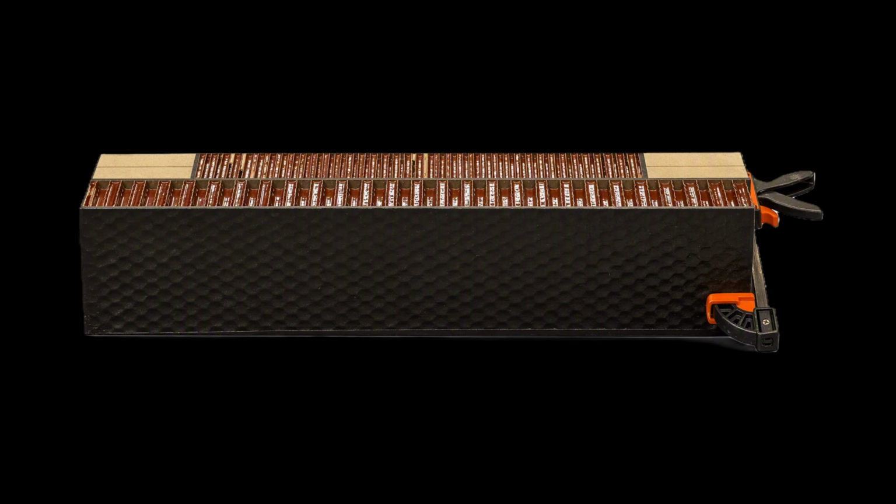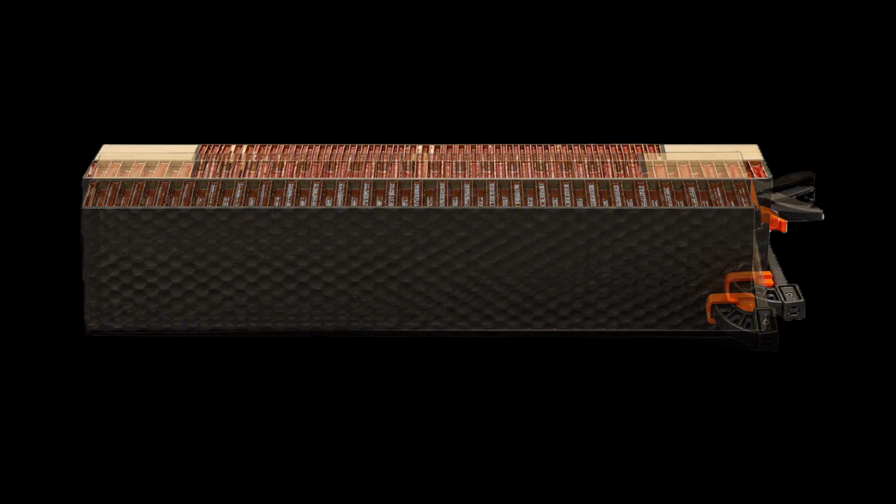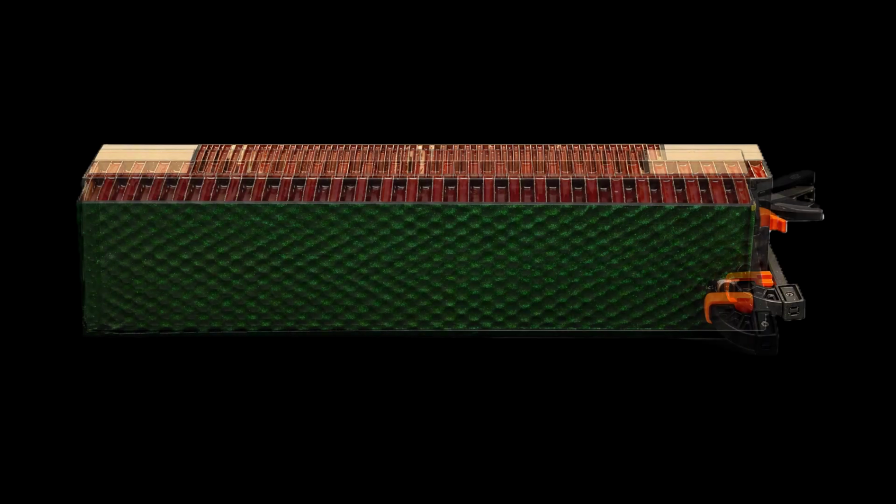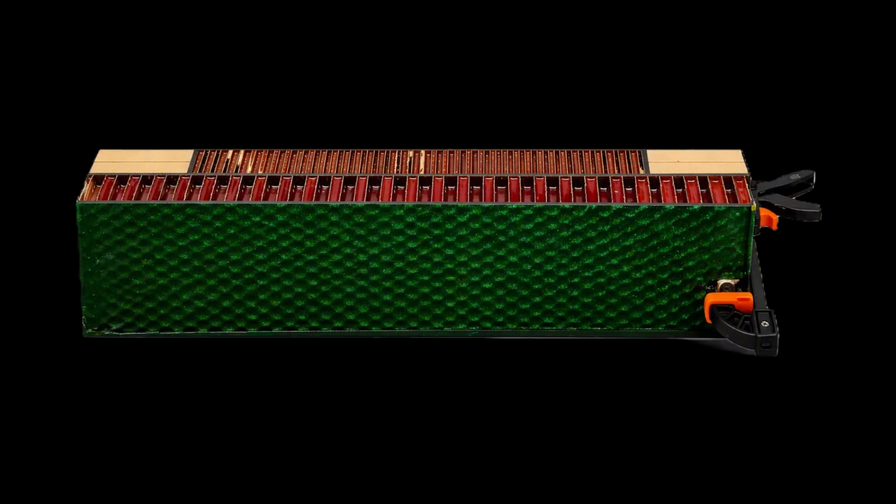In this ShearMap application example, we're going to look at a Honeycomb Composite panel with 3 fabricated delamination patches of varying sizes, where the smallest one is just at 1 cell. This is a similar type of material as the European Space Agency wants to use on the black upper stage of their new Ariane rockets, as it is both more durable and lighter than metal.